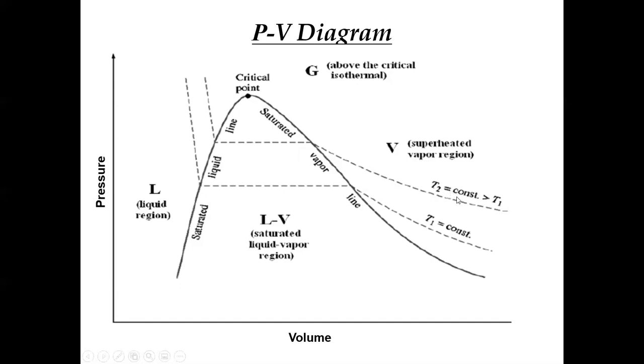These are lines of constant temperature. So on a PV diagram, you need to know how to draw an isotherm. Basically, this represents the same temperature. As I keep that temperature and pressure falls, say I've got a piston cylinder and I allow the pressure to drop, then the volume will expand a little bit. If I do it right, there may be some heat transfer involved, whatever it takes to maintain the temperature. As pressure drops, specific volume will increase a little bit, right? As I take pressure off the system, it grows a small amount.